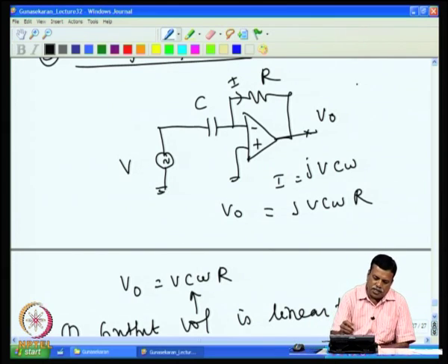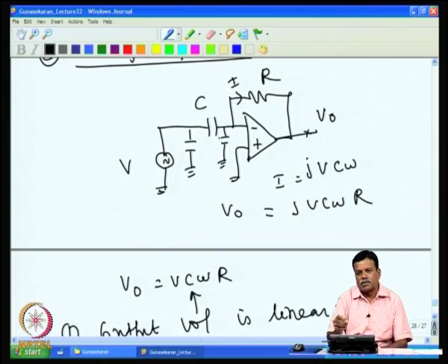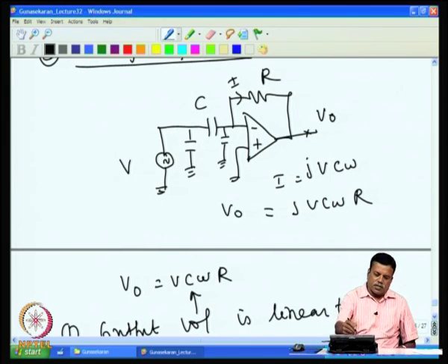Now, from our earlier discussion, stray capacitance is always associated with any measuring capacitance, because you will have a capacitance from this point to ground, mostly shield capacitance if you are using shielded wire. So we will always have these two stray capacitances with any capacitor. That is why capacitor measurement is always considered a 3 terminal measurement: you have a ground terminal 3, and measurement terminal 1 and measurement terminal 2.